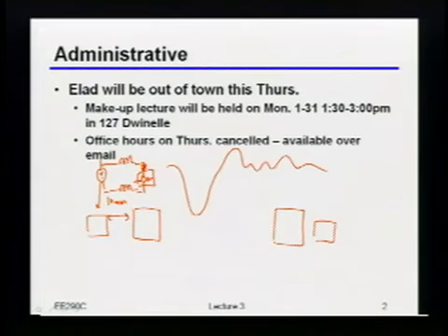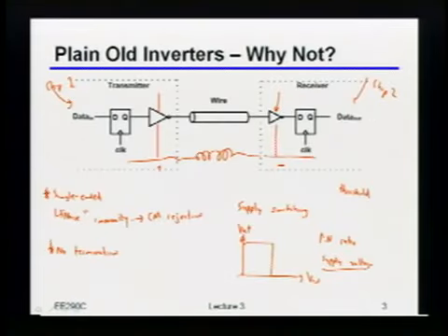L dI/dt. Yeah, it just says, no way, sorry. If you want that much current change, then I'm going to cause a huge change in the voltage, right? So let's actually even draw the full circuit over here. But don't you have bypass caps for that? Great, you said, don't you have bypass caps for that? Well, guess what? You're absolutely right, I have bypass caps. So let me even put bypass caps.